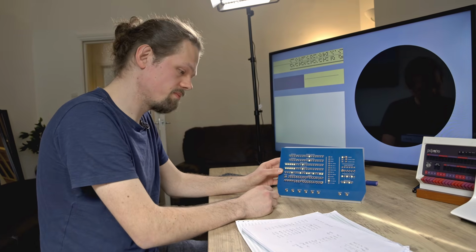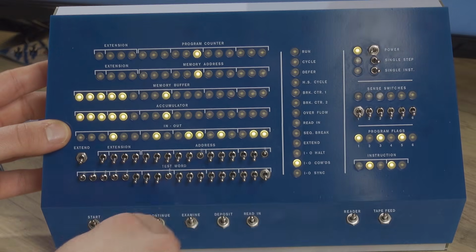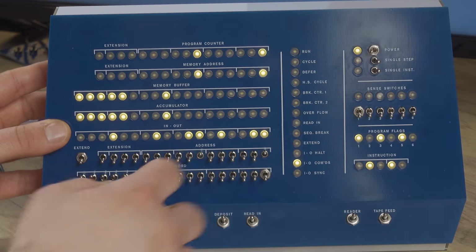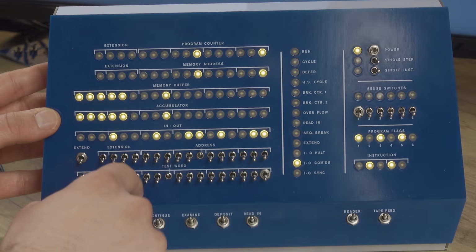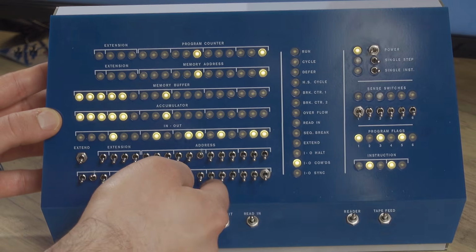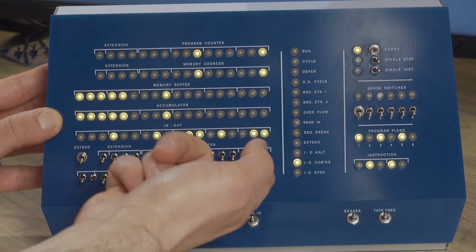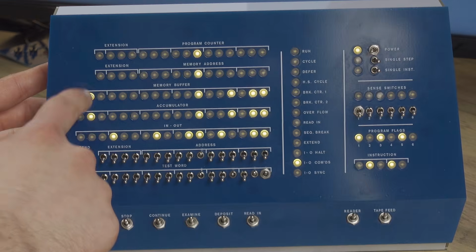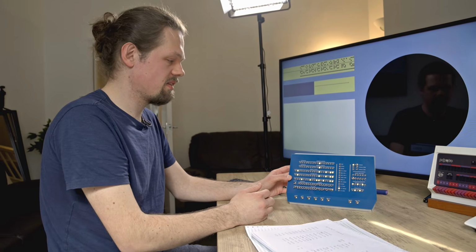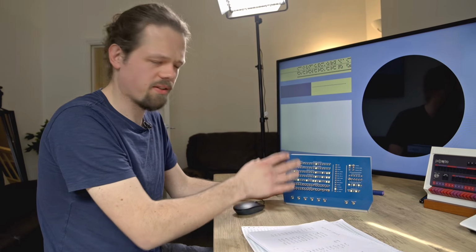That's the second instruction. That's no problem. We could just change the address and put it in location 101 instead. Easy. But now we have to do the first instruction, of course. So that is 200113. So you can already tell it's easy to make mistakes. And that is why I don't really want to do this on the front panel so much.